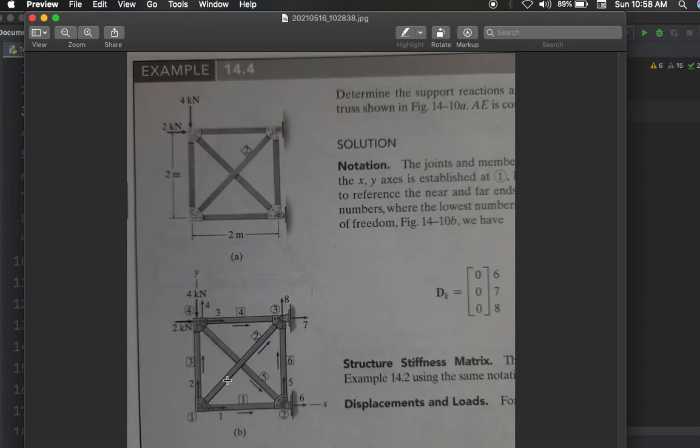So you have the freedom to number the free, unrestrained joints within the range available below. What is the range? 1 to 5. And you could have numbered this like 6 here, 7 here, and 8 here, but you could not put 5 here and 1 or 2 there. I hope you get that idea. If you still don't get it, please pick up the book. This example I have taken is from the book Structural Analysis by R.C. Hibbeler. So you have to understand this part first.